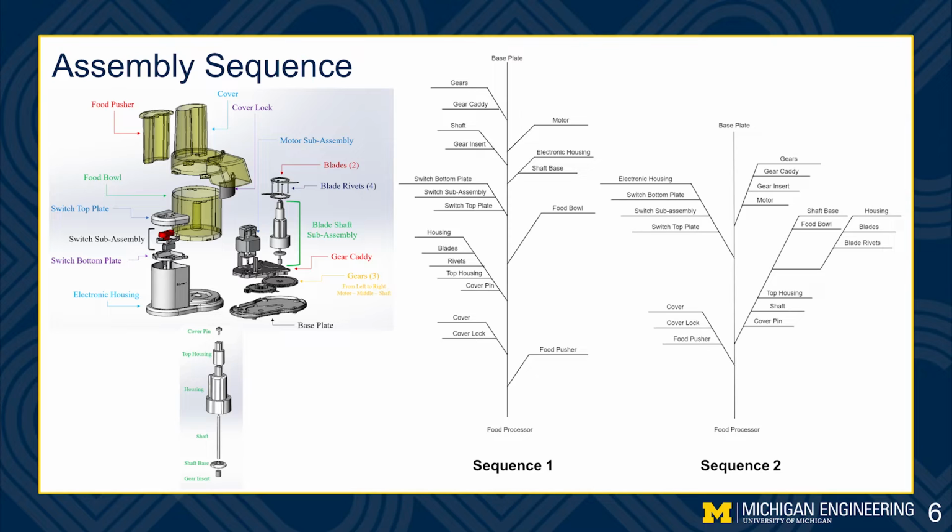Sequence 1 is broken up into more branches, which allows for better parallel assembly than Sequence 2, since it allows multiple people to work on various components, which can be easily secured to the main body later. However, Sequence 2 is better for transferring and handling, locating parts, and testing each subassembly as there are fewer parts moving around between people within the assembly line and it combines necessary components for testing. For example, the gears cannot be fully tested for binding without the motor in Sequence 1 until it is transferred to the third person in the assembly line, while in Sequence 2 it can be fully tested before being transferred to the next person. For fastening and joining components, both assembly sequences will have the same level of difficulty since how they are assembled does not change overall.